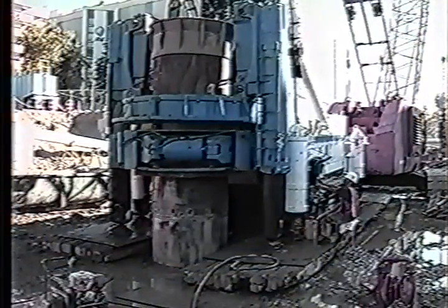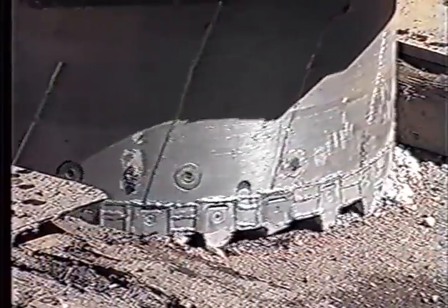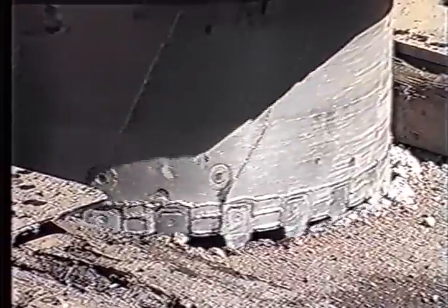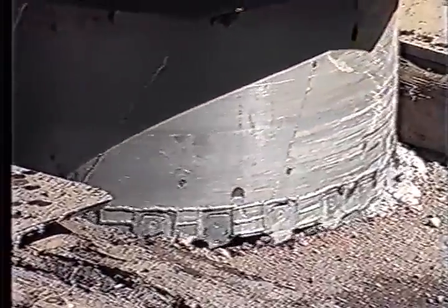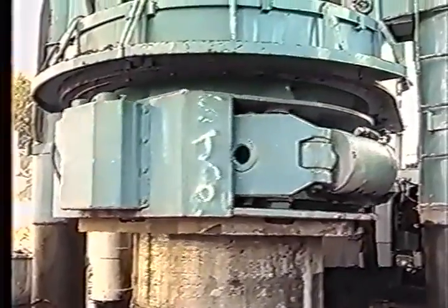In the 1980s, a new generation of hydraulic rotator machines was developed with a maximum torque of 6 million foot-pounds combined with a full 360-degree rotation capacity. This machine utilizes a cutting shoe with teeth optimized for cutting in one direction only. As a result, this system enables the casing to penetrate difficult soils, boulders, and rock sockets. These one-directional rotators are about 30% faster than traditional casing oscillators.